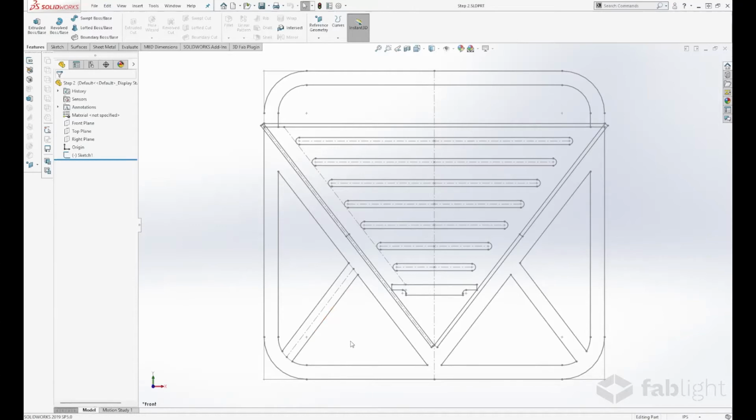This is really bulky material, really heavy. So we want to be able to reduce as much weight as possible while still being really functional and stable, right? We also added some additional slots here, and these are just tangent, again, to another parallel line that's been offset by about 1/2 inch. And this is to create some airflow through this grill face here.